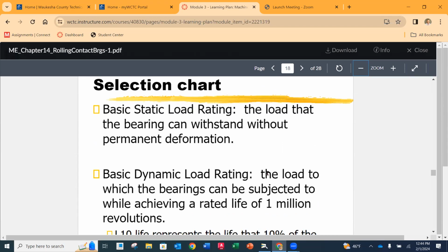But the other part of this is when we do our shaft design, we are going to be sizing for minimum shaft diameters. Those minimum shaft diameters say we need this much shaft material in order to resist those loads. And when we are at our bearing locations or at our supports, we're going to have a minimum shaft diameter that we also have to keep in mind. So we not only have to worry about load, but we also have to worry about the minimum shaft diameter.